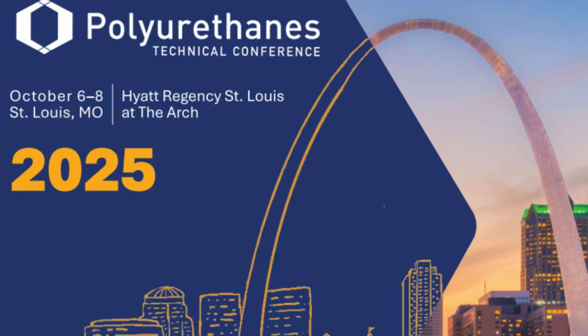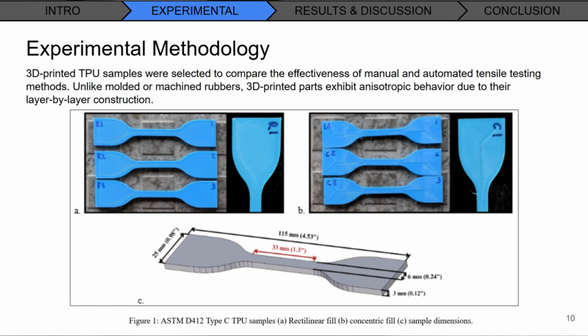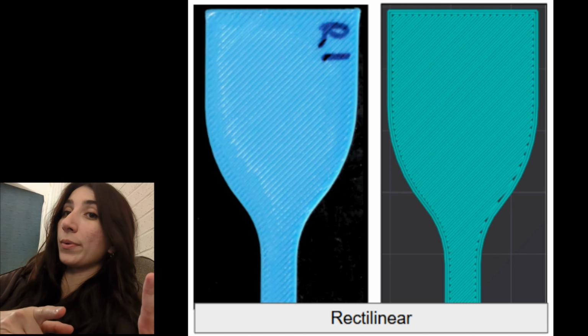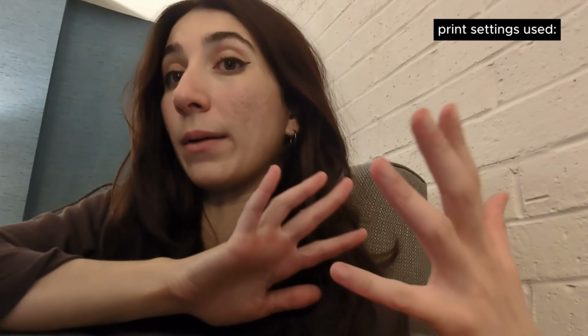For a technical conference, I gave a presentation comparing a manual tensile testing system to an automated system. I tested 2 different 3D printed TPU samples, one with rectilinear 100% infill and one with concentric 100% infill, at a 0.2mm layer height, 0.4mm nozzle, and the default print settings of 95A TPU on the Bambu Lab X1C.